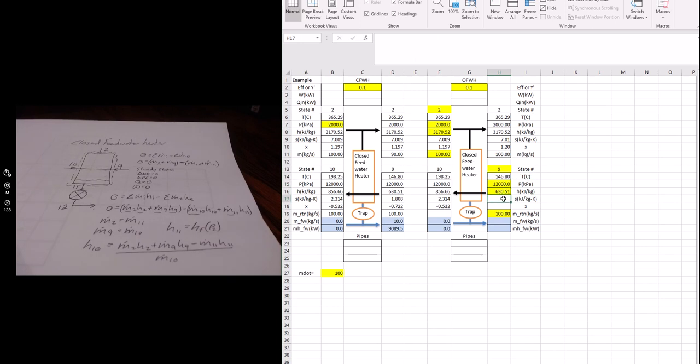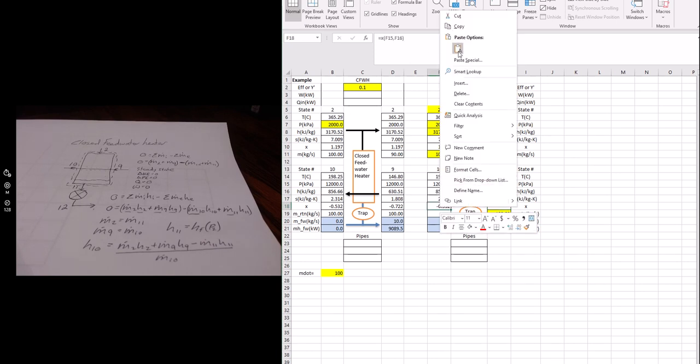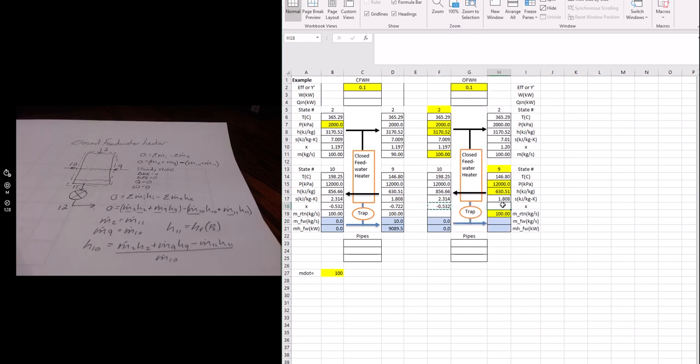And then equals water, pressure and enthalpy. I want entropy, specify the pressure and the enthalpy. And the quality, I can just copy this formula. Copy, and if I paste the first one, it'll reference these values, which is what I should have done there.